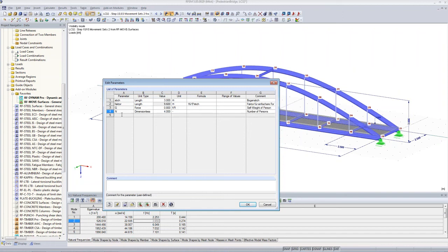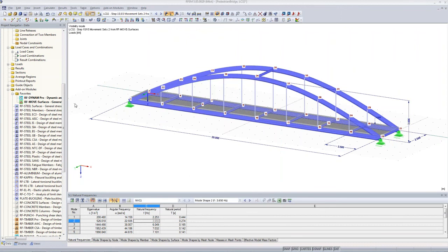And then we have the step frequency, which is Fs. There's no frequency unit available here, but it doesn't really matter in our case, so I just choose dimensionless, and we start with 2 Hertz. So we study a frequency of 2 Hertz, the step frequency. I just make a note here that this is actually in Hertz, so that I don't forget. And this is all the parameters I want to define.